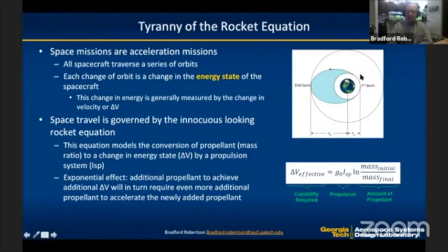And so you can see here, this is the basic example of a very basic orbit transfer. You would have one burn to raise your orbit, and a second burn to circularize into a higher orbit. Generally, what we refer to as each of these burns is the change in velocity at each section, otherwise known as delta V.